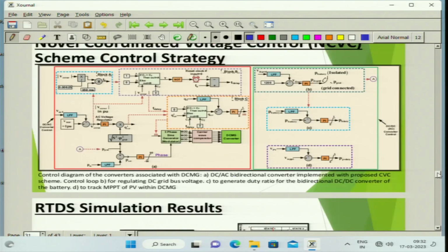Now, this is just the execution of whatever I have told on the RTDS platform. There are different blocks in the implementation. First of all, we calculate the change in the error in voltage at a specific bus, and this is the delay time that needs to be executed. And then we reset the clock. That means, if there is a change in voltage, the clock will begin to ensure that we wait for such time. There is a clock we have inserted. So, once this clock is done,